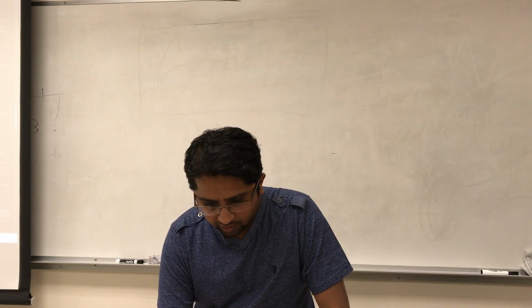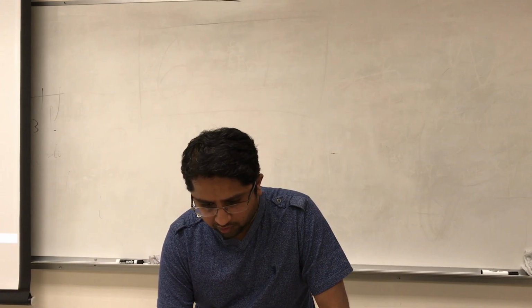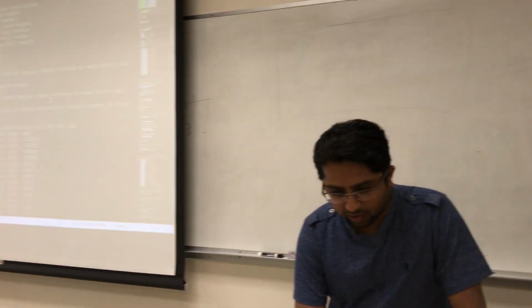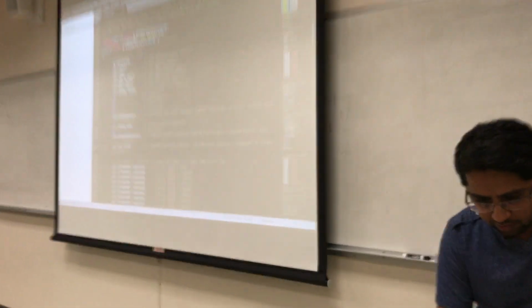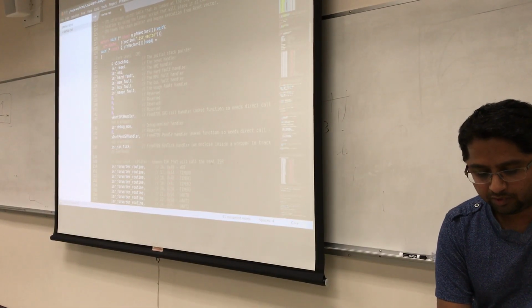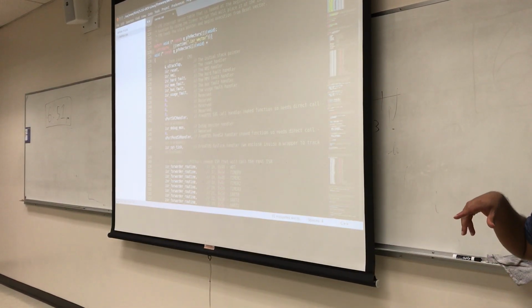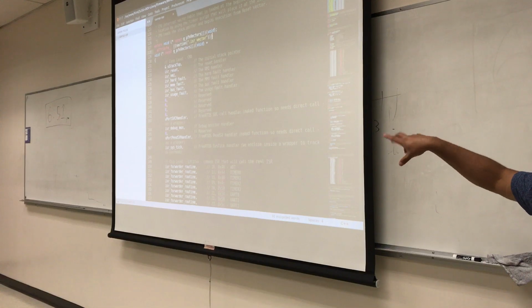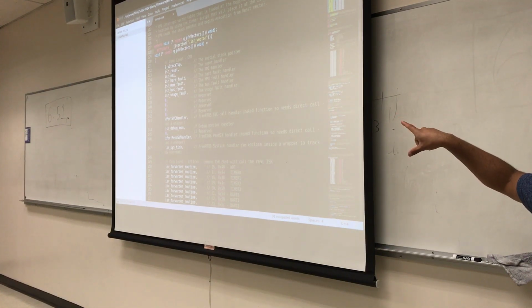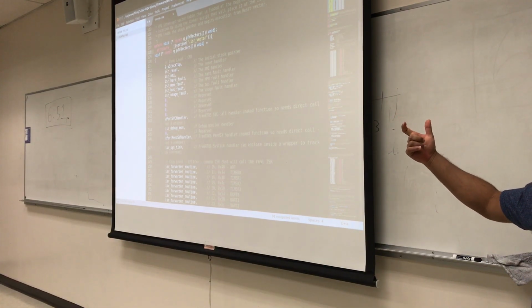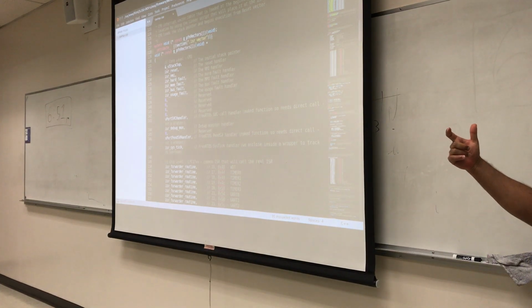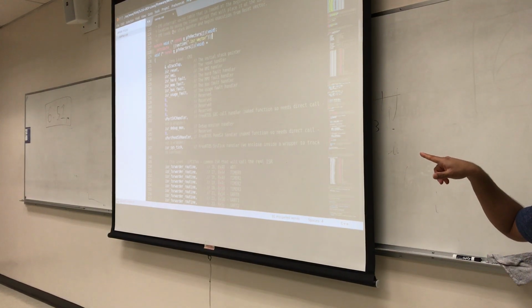Then look at the keyword in line 128. It says attribute section .isr_vector. All the information inside the function array has all your interrupt system in there.